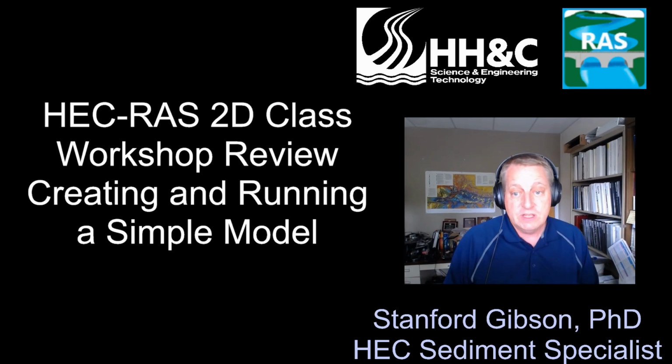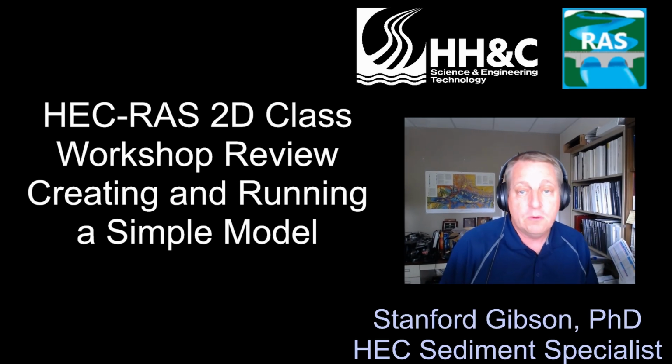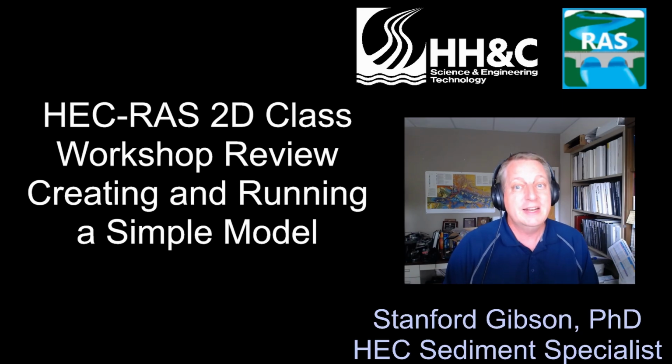There's a second half of this workshop where we're going to go in and refine the model. We'll play around with cell size, we'll play around with time step, we'll play around with break lines to move from this kind of simple model that I actually, despite the subgrid, wouldn't necessarily give to anyone, to something that's a little bit more robust and start comparing results.